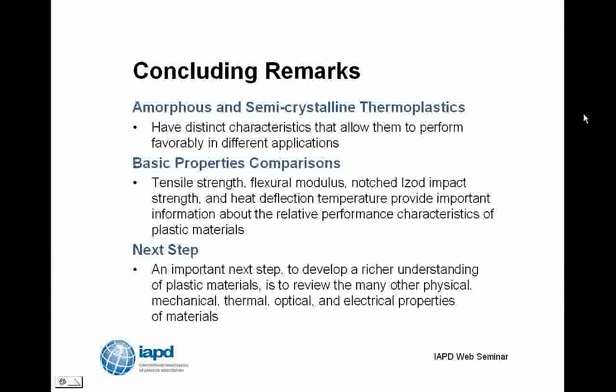The strength, stiffness, toughness, and heat deflection temperature of a plastic provide important information about the relative performance characteristics of plastic materials. How does nylon compare with polycarbonate? How does Teflon compare with acrylic? And when you overlay those two ideas, you really are a step closer to doing a very solid material selection.